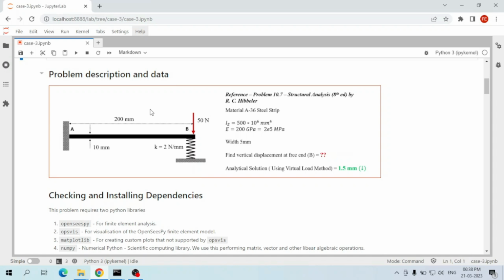For example, boundary conditions such as rigid fixed supports do not allow any translation or rotation like this one. Hence, we put 0 for translation and rotation at fixed supports. Another interesting scenario is pinned support or hinge support. It resists the translation, but it cannot resist the rotation. Hence, we put 0 for translation DOFs and let the member rotate to any degree.